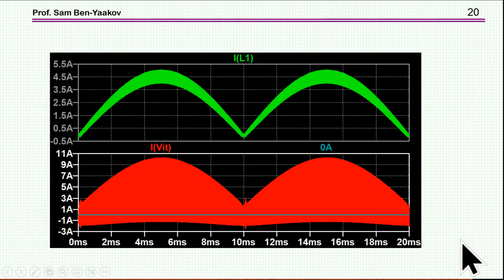And here is the overall result. This is already the inductor current. So we see here the ripple, and again this upper side is following the input, and this is now the combined signal or combined current of the input plus the ripple coming from the small inductor.